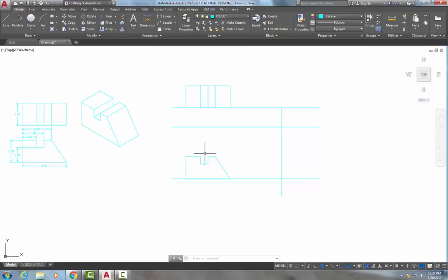Keeping in mind that if I want to see less of the top, the way that I could take care of that is I could move my ground line up some, or I can move my vertical line that has my station point and my horizon line on it over to the right some. Also, if I want to see less of the right side, I can move this vertical line left. That would be a couple ways I could solve it.